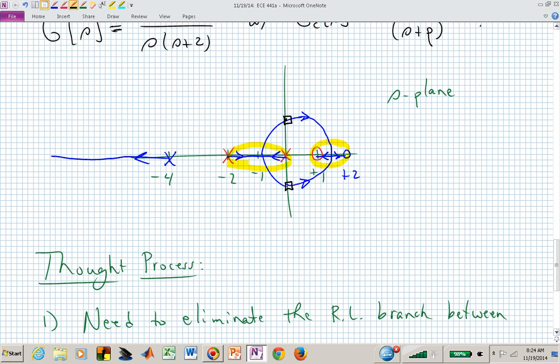There's two conditions, aren't there? When you're studying for this exam, there's the magnitude condition and the phase condition. Which one would you use to convince me that the root locus is at that point on the imaginary axis, or not? You would be given that point. So if you're given that point, let's say, and you could find it, couldn't you? You could find it with the root array. You could find it algebraically. You could find it by using the phase condition.